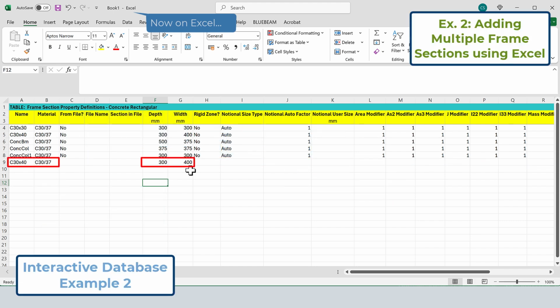For illustrative purposes, let's proceed from the assumption that the width is the dimension changing, and is now 50 centimeters for this new section. As stressed a few moments ago, make sure to also change the name of the new section, if you want to avoid the data being ignored or incorrectly assumed.